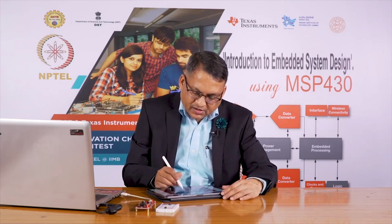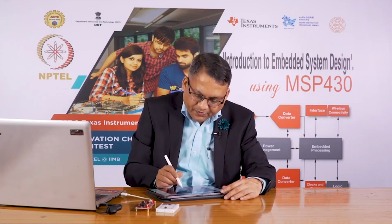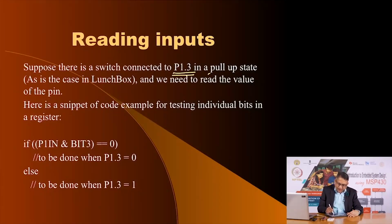Now, in our case, on our lunch box we have a switch available, and it has been connected to P 1.3, and an external resistor has been used in the pull up state. Therefore, we should ensure that our program takes cognizance of this feature: a switch is connected to P 1.3, a pull up resistor has been used, and so the program must appropriately recognize this configuration.